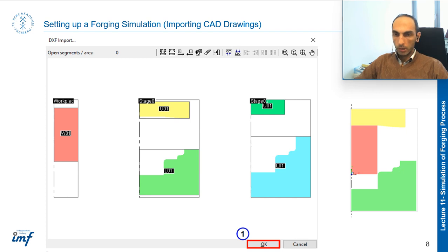Because in 2D, the number of mesh elements you can use is higher, and the computation time is lower than 3D. And from the point of view of accuracy, even in 2D, if you set up your simulation well, you can obtain an accurate prediction.